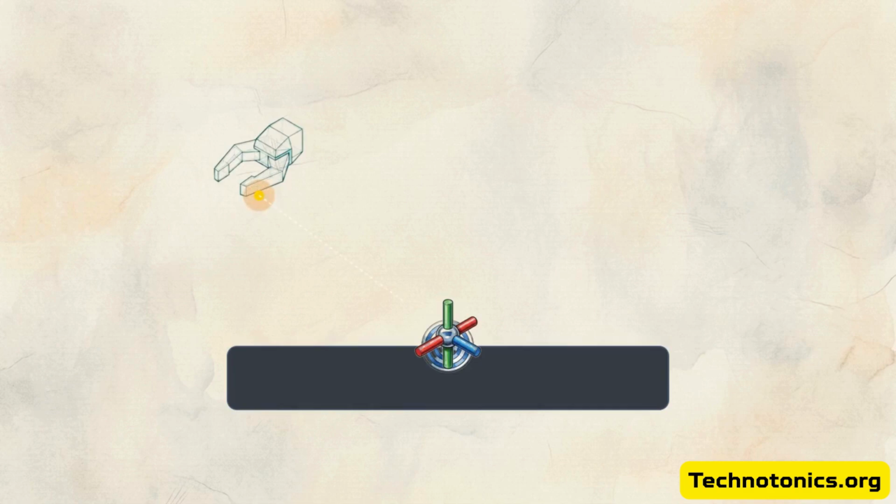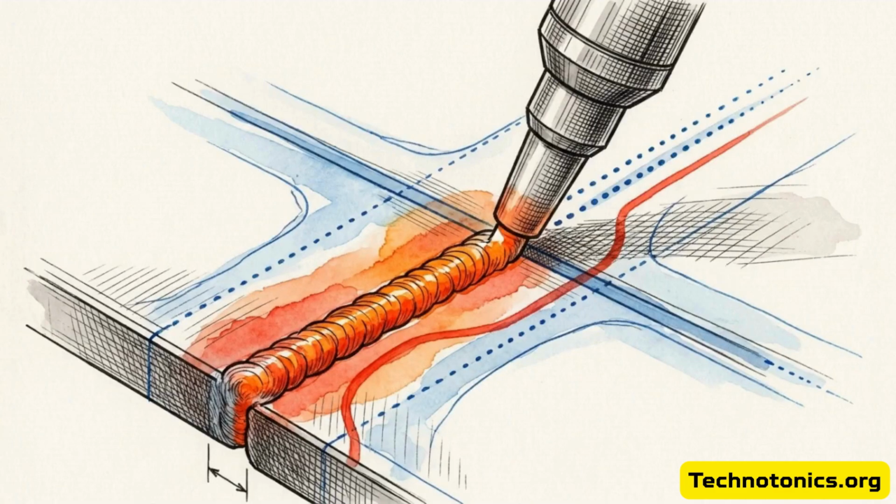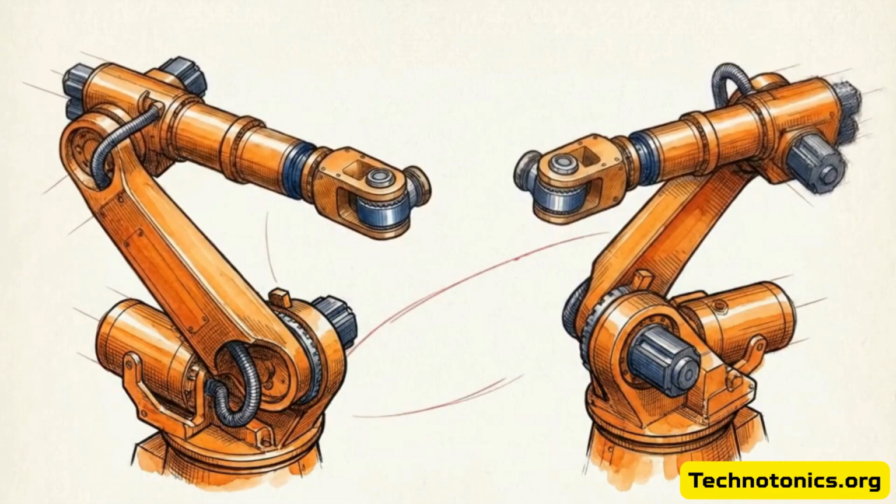We verify this alignment with a dry run. The TCP must strike the exact target coordinate on the virtual workpiece without any deviation. If a robot repeatedly misses a target while executing what looks like a precise movement, a misaligned coordinate system is almost always the hidden cause. In complex physical factory layouts, operating blindly leads to heavy industrial arms colliding midair, causing massive hardware damage.